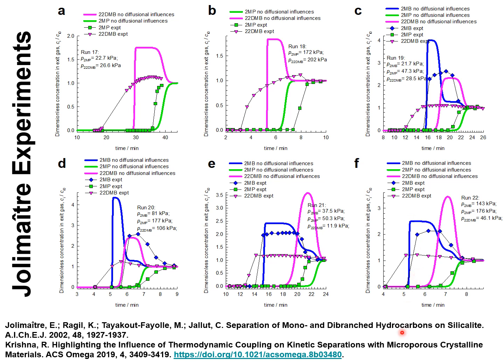And this is also helpful in the separations because we want to recover 2,2-dimethyl butane for incorporation into the gasoline pool, and due to diffusional influences, the component to elute first and recovered in the raffinate phase is 2,2-dimethyl butane. So diffusional influences help separations. Let us demonstrate that quantitatively in the next slide.